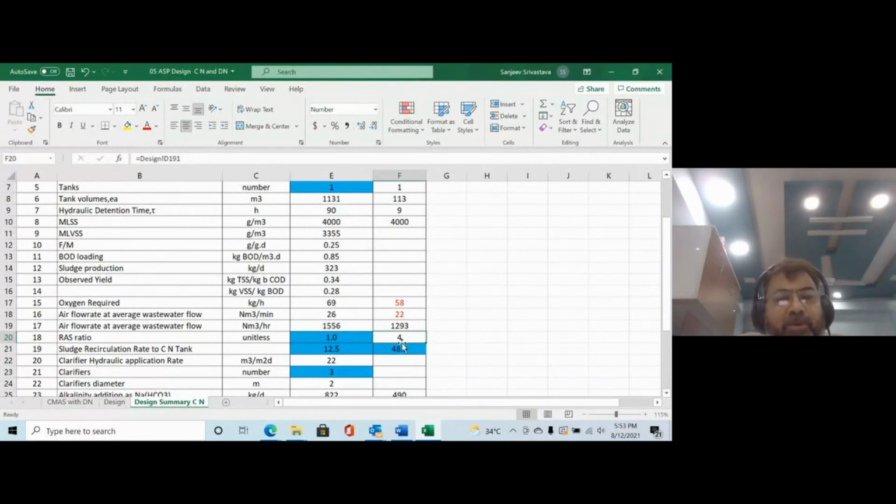For example, in one of the tenders I was working on, the initial nitrate level was 25. Nitrate, NO3. I'm not talking about ammonium nitrogen or Kjeldahl nitrogen, and the river water nitrate also could sometimes be 6, 7, 8. Now, if you say your treated water TN should be less than 5, then what the hell are we talking about? We are talking about taking the water from the river and converting nitrate to N2. It is practically a rubbish thing. But if the tender is like that, then you are in problem.